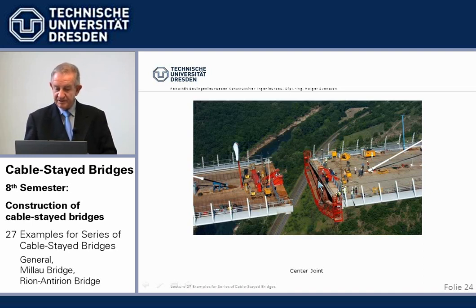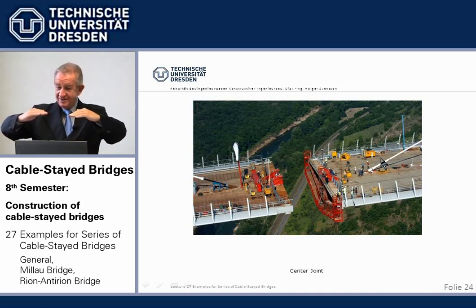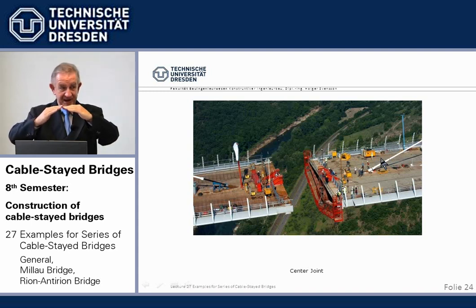We come then close to the closure joint to adjust very carefully. Of course, it helps here immensely to be able, in this case, to pull at the cables. You know, normally, with cantilevers 170 meters each side, you do not come exactly; you need to be in level, and you have to have the right angle.